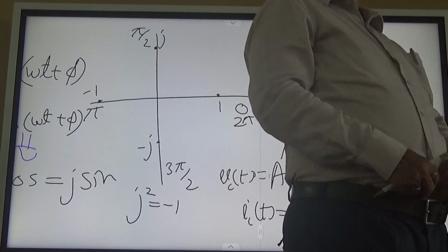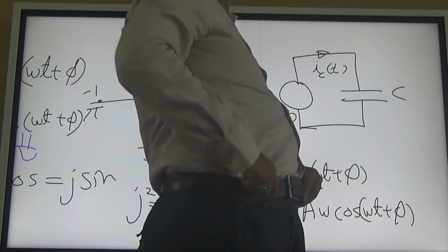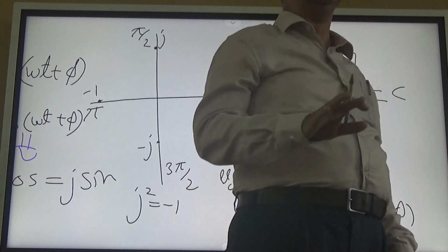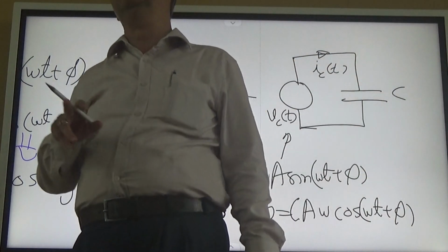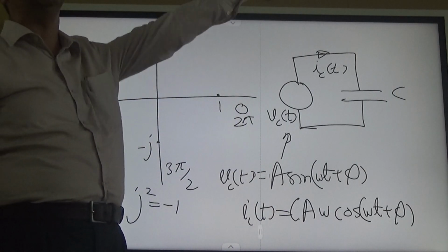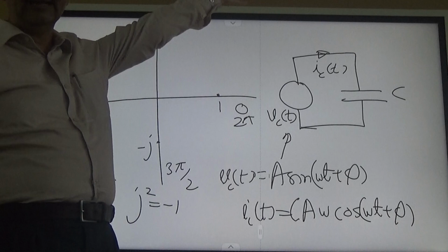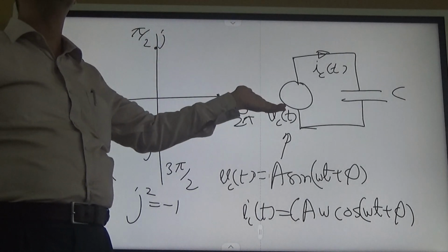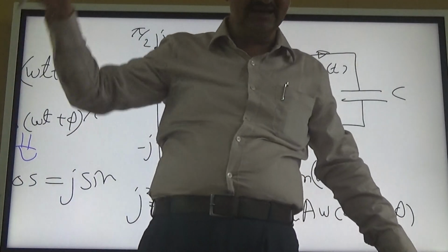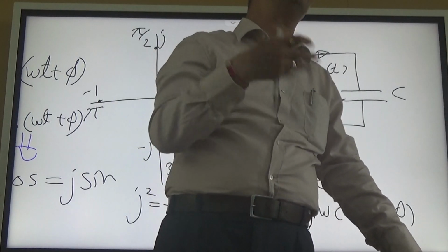Actually, if the ratio is taken, for a resistor there will always be a constant ratio, whereas for a capacitor the instantaneous ratio is different. Tan means what will happen? Sometimes voltage is there, no current. Sometimes current is there but no instantaneous voltage. If you plot the voltage signal and current signal instant by instant, you find the ratios will be different. So there is no point in putting tan.